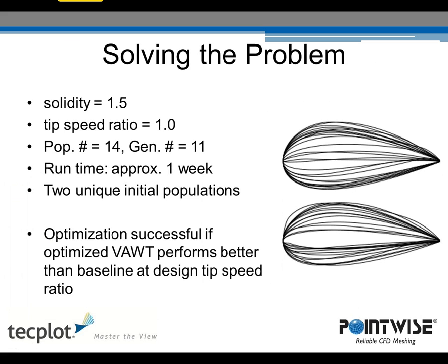The optimization algorithm chosen for this study was an in-house differential evolution algorithm. It's a stochastic direct search method where the parameters, mainly the airfoil parameters, are represented by floating point values rather than binary strings like in some evolutionary algorithms. It doesn't require the problem to be differentiable or continuous as is required by local gradient-based methods. This makes it attractive for design optimization where the characteristics of the solution space may not be known beforehand. It's also very fast because each objective function evaluation can be done in parallel.